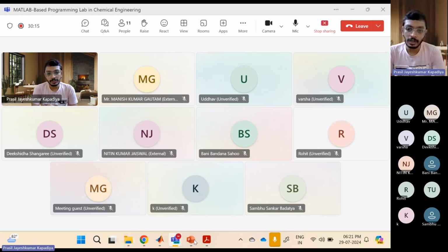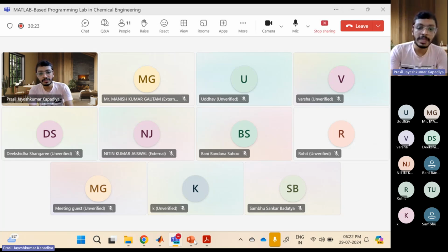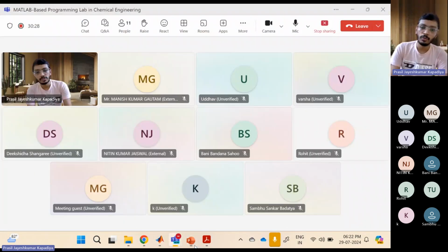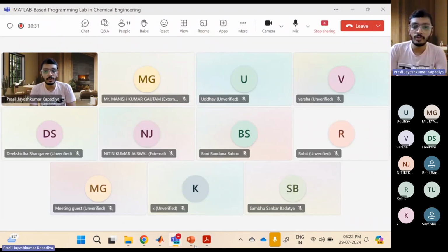So if corrosion is occurring, we should pass it through the tube, as Rohit said. You are correct. But other than corrosion, what is the main factor we have here? We have very high pressure. So to avoid any kind of unwanted events, we pass it through the tube. What happens when I pass the corrosive material through the tube? It is easier to clean it. Am I right? One is for safety purposes and second is for cleaning purposes.